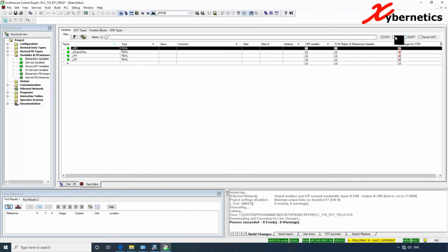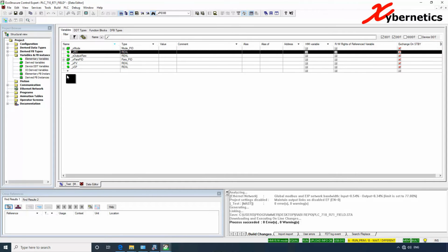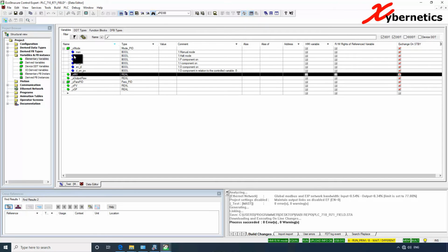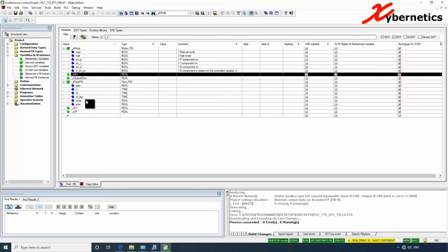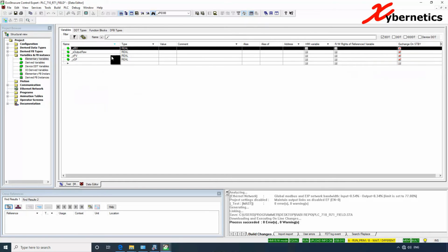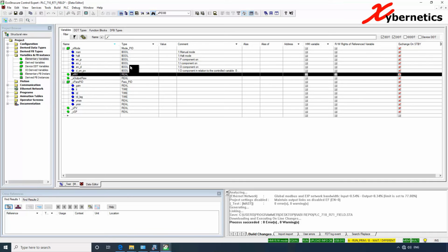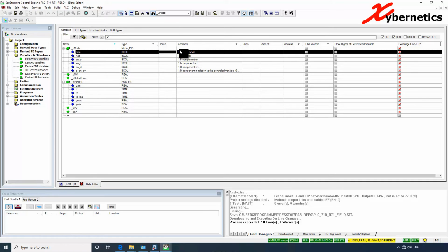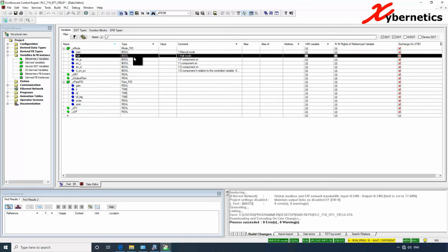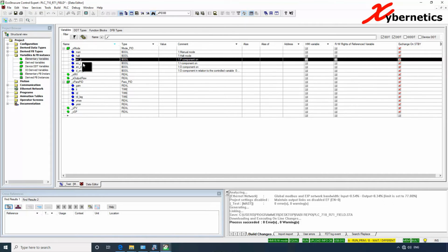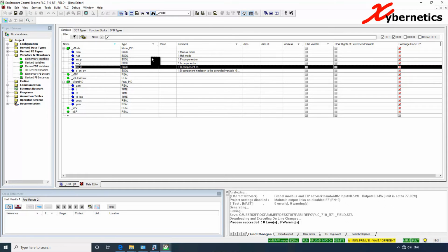Now to enable that, click on DDT, and then you can see all of them in here. You can see these are just raw values, right? I want to touch a bit based on this one here. The native ones are pretty straightforward, but the DDT ones are a bit different. In the world of Schneider Electric Control Expert, DDT is actually a structure. So you can see if you assign this to 1, which means it's manual. By right, it should be 0. Halt as 1 to halt the PID process. And you can enable the PID to allow you to do the control.